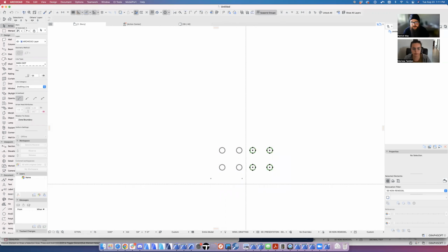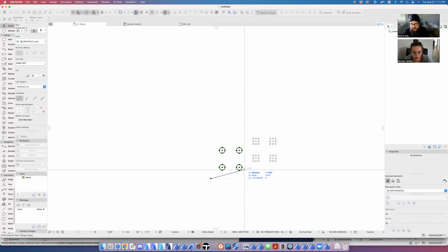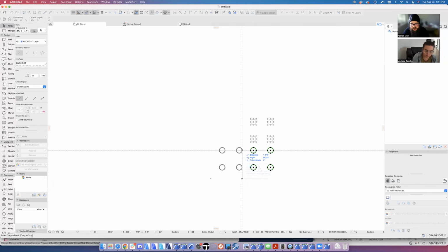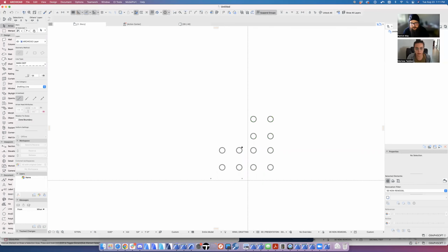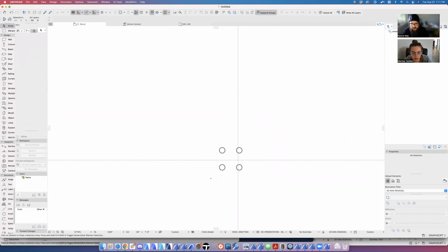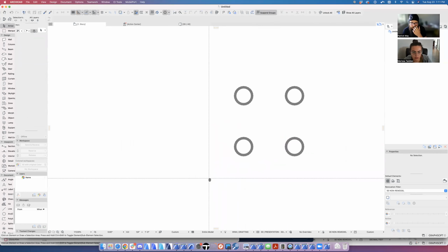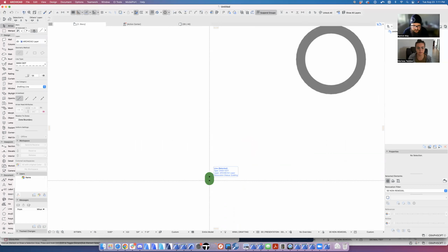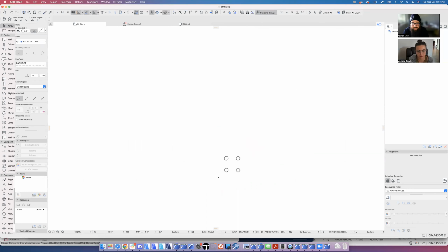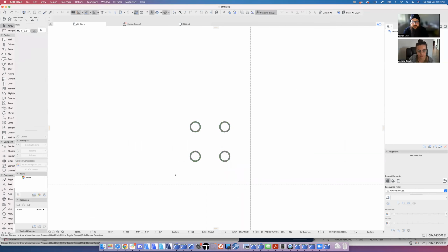So you just want to make sure that from this bottom origin point here, it's going to tile evenly from that point to here. And then when that gets copied up from this point to here, it's going to tile evenly. So this little 64th of an inch piece is kind of a dummy placeholder, and it does kind of get in the way. Did I make it 64? Yeah, it's as tiny as we can get. I don't know that you're going to actually see that in there, but this has been the best way I've seen to create this. Otherwise, you end up with weird spacing. So you could do it without.